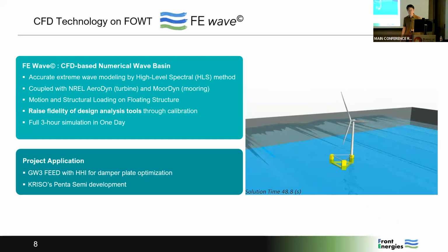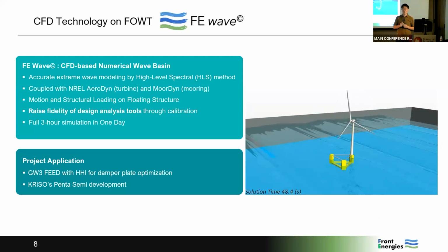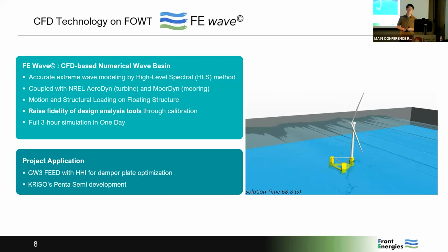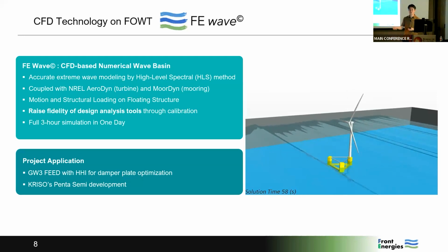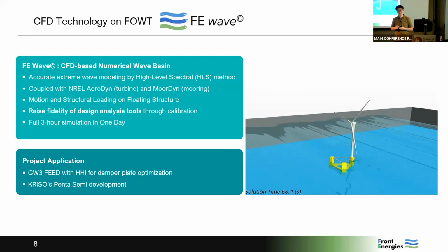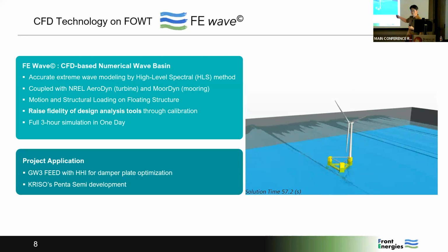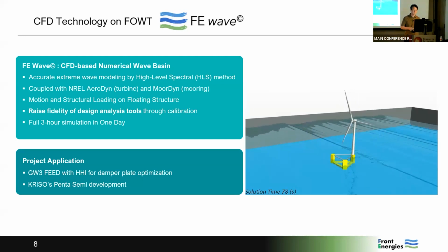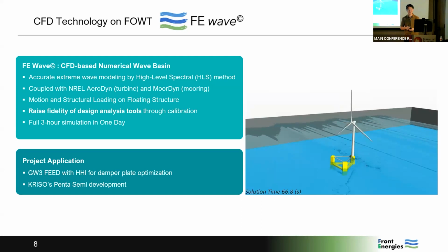We can do it. The important thing with CFD analysis is that usually when we design these floaters, we do a physical model test. For a physical model test, we need to occupy or reserve a slot in the physical model basin, which takes 6 months. They also need to prepare the model and all the settings, which takes 3 months. After the model test, we need to get some results, which takes 2 months. But with CFD, generating the model takes 1 day, and the CFD analysis takes 1 day, so we can get results in only 2 days. That's why we're focusing on CFD analysis. Even a 3 hour simulation takes 1 day. So we have some technical knowledge.